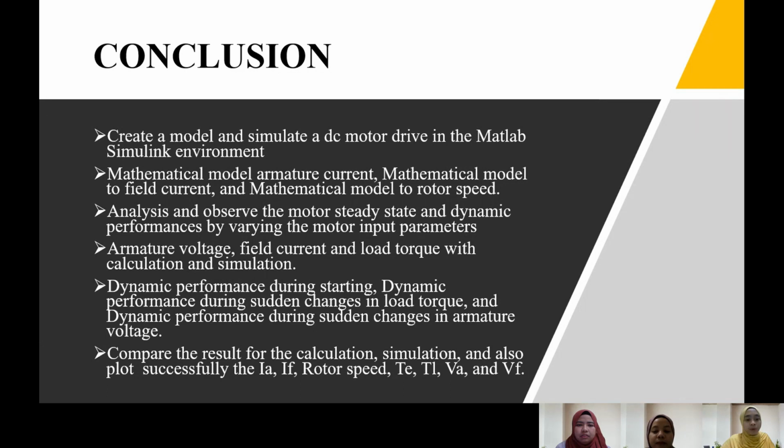This model was successfully simulated using MATLAB Simulink. Next, students are able to analyze and observe the motor steady state and dynamic performance by varying the motor input parameters such as the armature voltage, field current, and load torque with calculation and simulation.